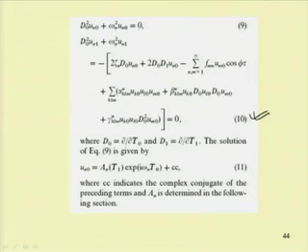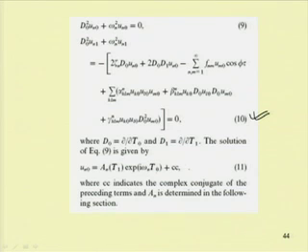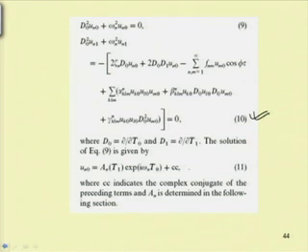So, the solution of this can be written as A_n(T_1) e to the power i omega_n T_0 plus its complex conjugate. Now, substituting this equation in this equation, one can see it will contain several secular terms, and in addition to that there will be some mixed secular terms. So, these mixed secular terms will come when we consider this phi equal to 2 omega_1 plus epsilon sigma_1, and in this particular case we have considered the internal resonance also.